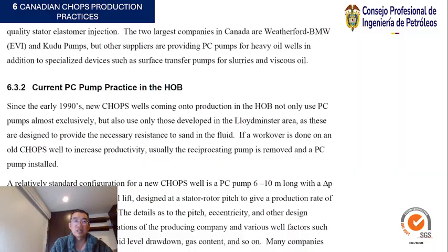6.3.2 Current PC pump practice in the HOB. Since the early 1990s, new CHOPS wells coming onto production in the HOB not only use PC pumps almost exclusively, but also use only those developed in the area, as these are designed to provide the necessary resistance to sand in the fluid.